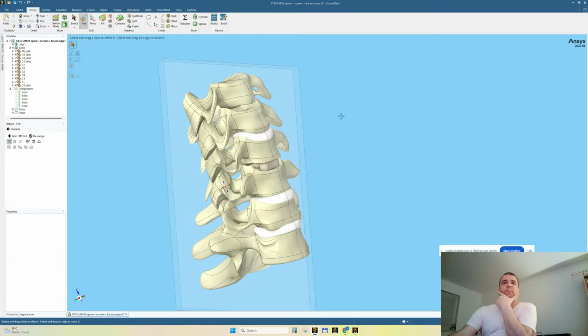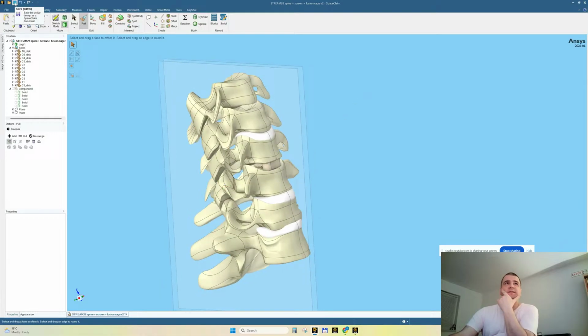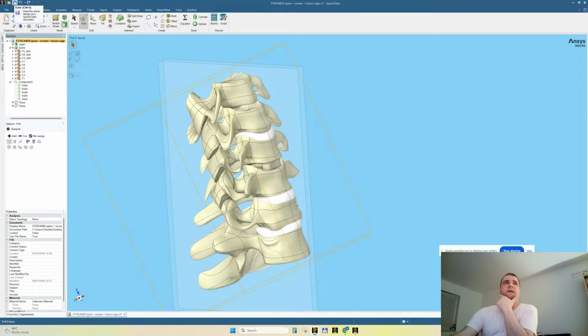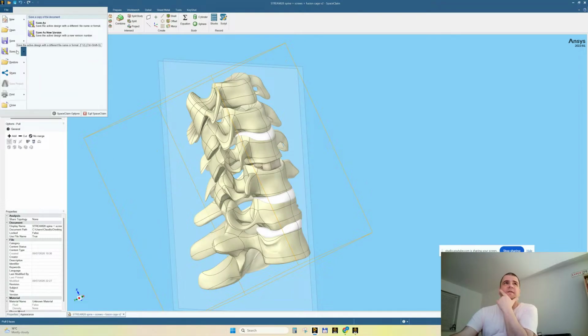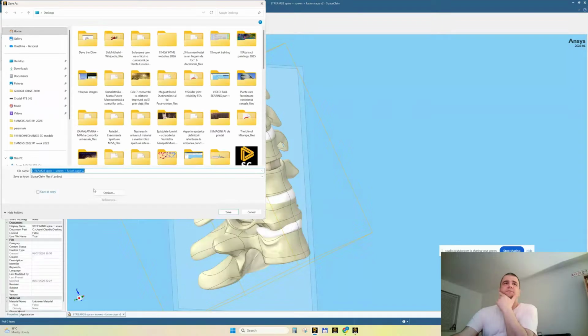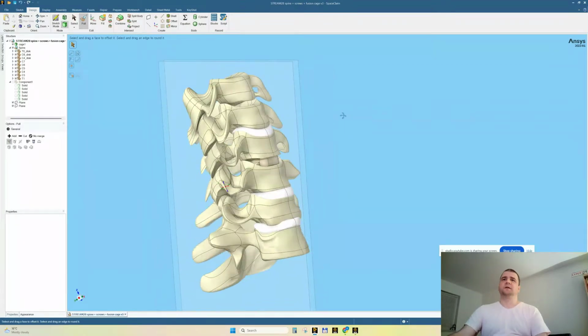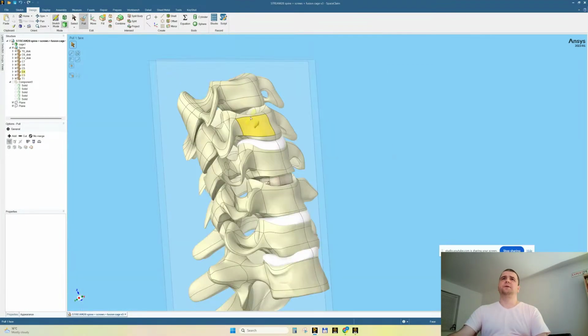There is a very simple command now. Let's hit save. Source internalize all. Delete empty components. Let's hit save, because I'd like to create a third version. This is the most important version. Because we're going to make Boolean operations to combine the parts, the modifications are, let's say, irreversible. This is why you need to create multiple versions in case we mistake something.